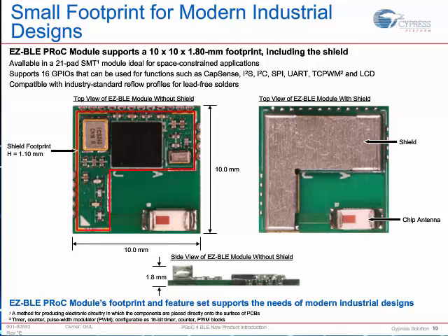and it allows you to save the time and the cost that you would otherwise need if you were taking a chip and then adding your own antenna and your own crystals to it, because you would have to go through the certification and qualification processes from both the Bluetooth SIG and various regulatory authorities like the FCC, CE, and so on. So modules are great for people who are looking to create products in a minimal amount of time or with minimal investment of board and hardware design resources.